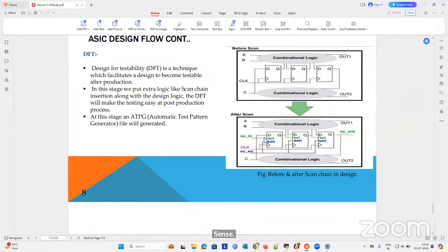But while manufacturing the chip, we may lose connectivity, or there may be some violations due to which the logic fails. To avoid this mismatch in the design failures, we use scan pins. Whether the cell is working correctly or not, using these scan pins or scan cells, we will directly check the logical behavior of the circuit.